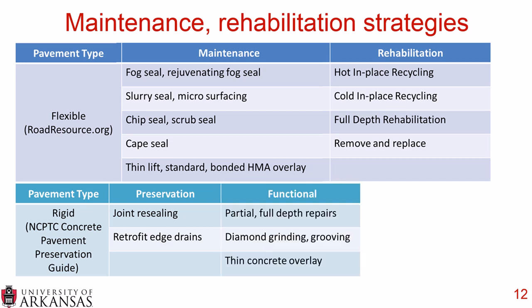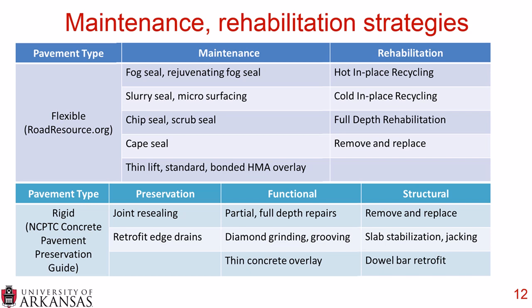Functional is kind of a combination of maintenance and rehabilitation. With functional, you can do partial or full depth repairs, you can do diamond grinding or diamond grooving, and you can do a thin concrete overlay. And then structural is squarely in rehabilitation. You can remove and replace, you can do soil stabilization or jacking, and you can perform a dowel bar retrofit.